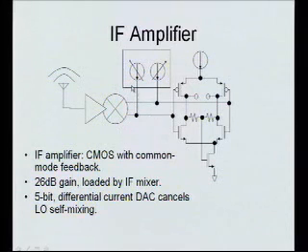So what that's saying is I have an oscillator, it's running, it's generating a 900 megahertz signal. That signal's on an off-chip inductor, so it's radiating. Can't help it. That radiates over onto my antenna, comes in, gets gained up by the amplifier, and then mixed down, and it's the same frequency, so it comes out at DC. There are various isolation tricks you can play to make that less, but you can't get rid of it. It's always there. And now if you follow it up with 30 dB more gain, you're almost guaranteed to clip. You're going to saturate, because 30 dB of any sort of DC is huge.